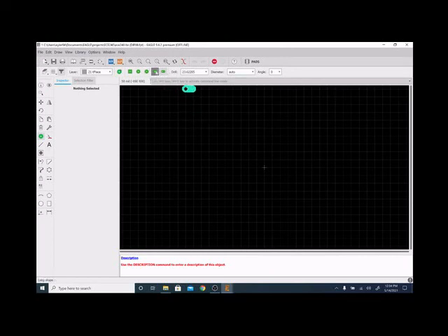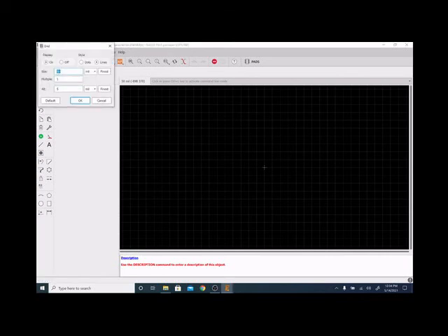But in this case, we're going to use what's called a long pin. And first off, I have to change my grid units here. So grid comes on naturally for the board layer, in this case the board layer that we're using to generate our footprint. So I'm going to go to the grid and change this to inches, and a standard pitch or spacing between pins for most parts is always 0.1 inches.